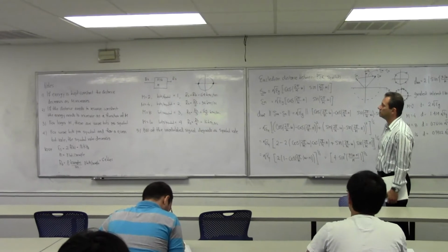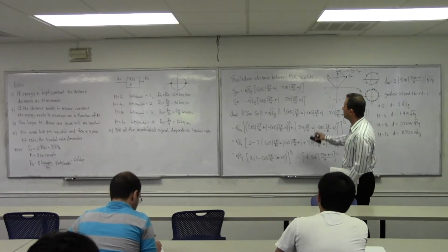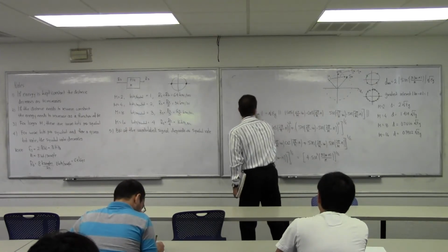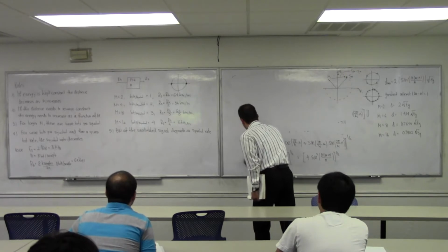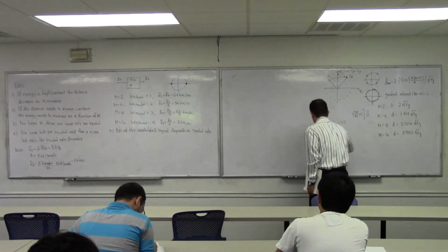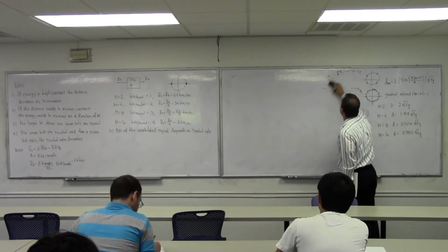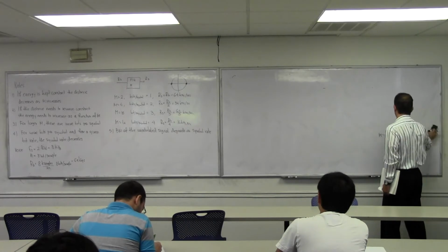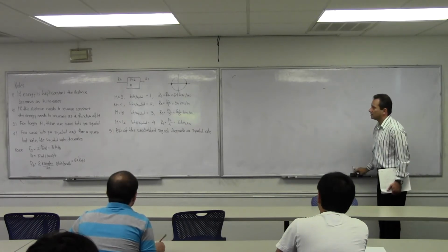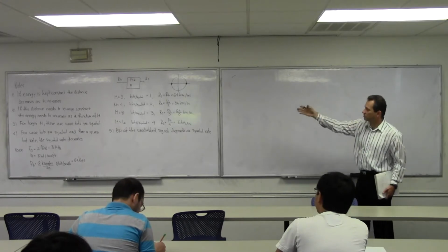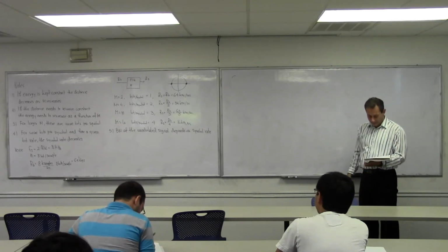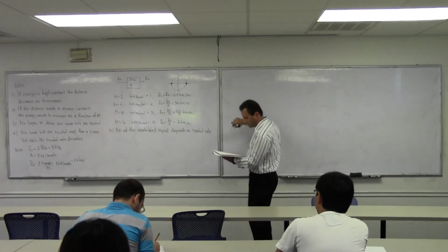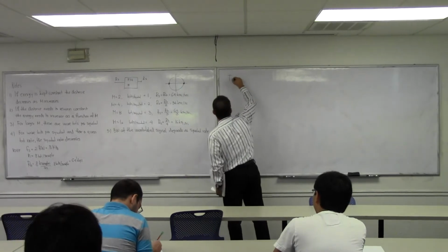using two-dimensional modulation where your basis vectors are sine and the cosine. There's an alternative one. And this one is called quadrature amplitude modulation. And this one is a more general type of the modulation. As a matter of fact, it will include the PSK as a special case, but we treat it separately because, you know, it is kind of used separately. It is either you use this or you use this, and the motivations are slightly different. Right, so two-dimensional signaling.